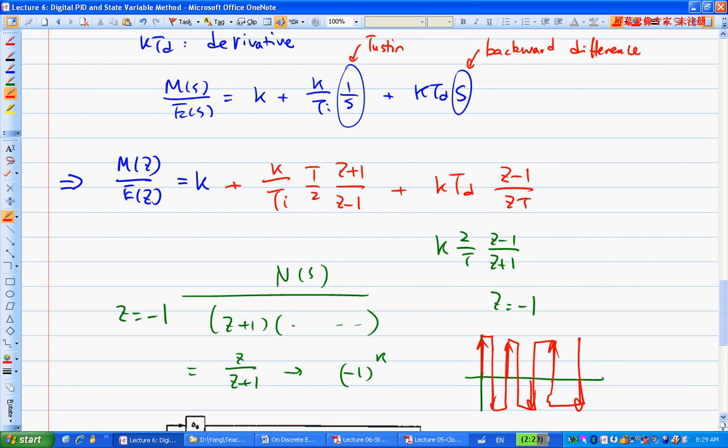Yes. So basically, this is called a ringing effect. Okay, a ringing effect. So the rule of thumb is you don't want to input to your system something oscillating. Why is that? Because let's say you have a motor, and your motor feels this oscillating. One moment is here, one moment is there. So this basically is trying to do this, right? And that's kind of damaging to the system. Okay, yeah. So you want your control input to be smooth, right?